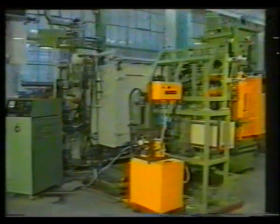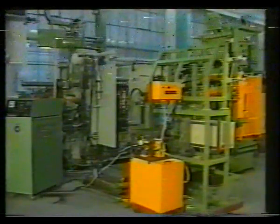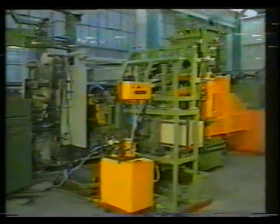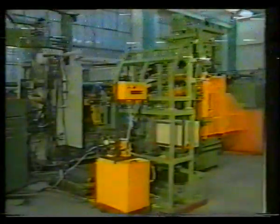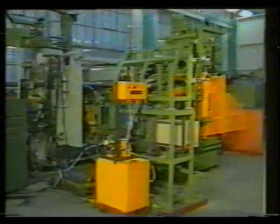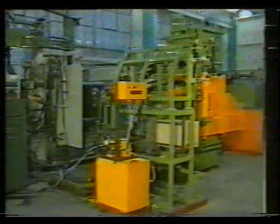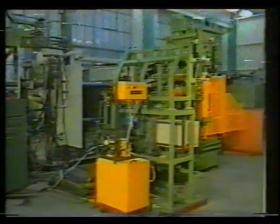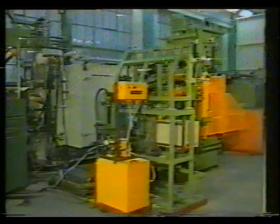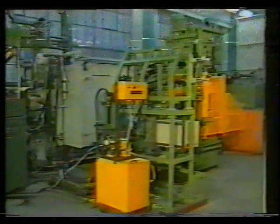The edge gating system was selected because only small lots are produced, but in a large variety of different types. The system is designed for casting rotors with different diameters, ranging from 55 up to 110 millimeters, and lamination stack heights from 25 to 140 millimeters. It allows production of a total of 160 different rotor types. For this reason, the entire system has been designed for quick and simple production changes.